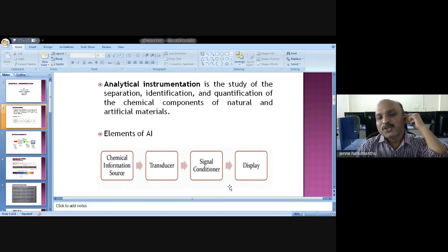So what can you do? You cannot transmit that very small signal. You have to amplify it. That output of the transducer should be amplified, sometimes attenuated. If any noise signal is present, you have to attenuate it, then transmit through some telemetry technique. So there should be some processing done on the output of the transducer. Who can do this processing, amplify and attenuate all these? We need an electronic circuit, nothing but the signal conditioner.